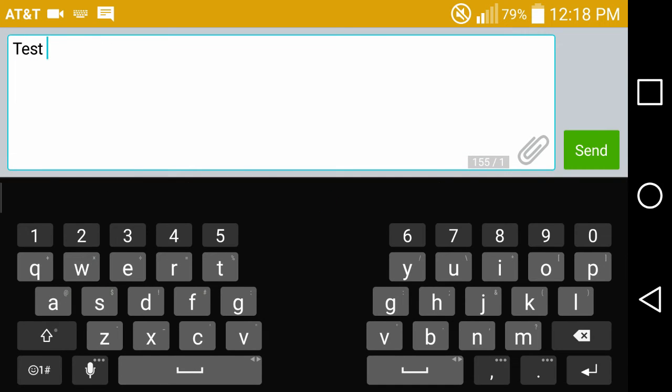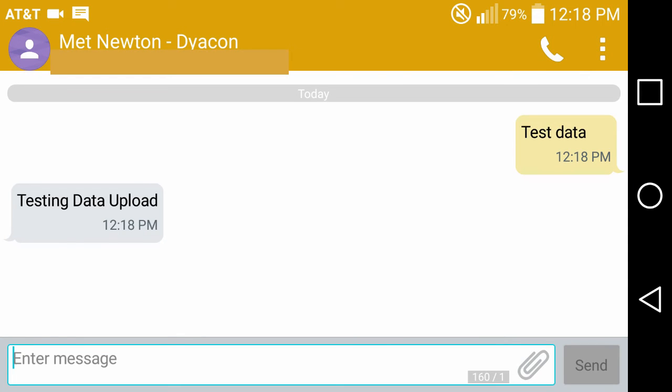When configuring the weather station to send log files by email or FTP, the test data command can be issued to force the weather station to send test messages to the configured servers. The weather station acknowledges receipt of the command but does not indicate success or failure. Users will need to verify that a test message or file has been received in their email or FTP servers.